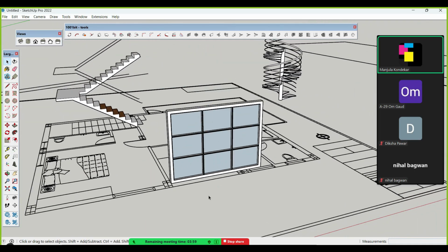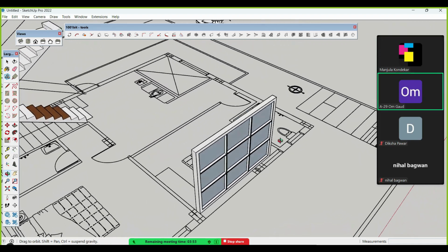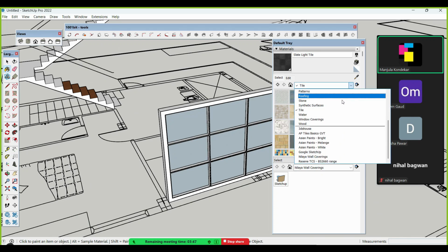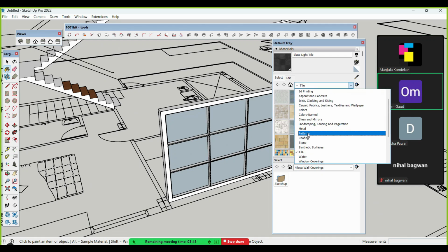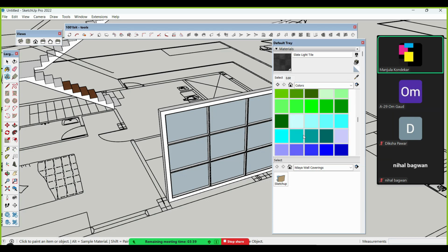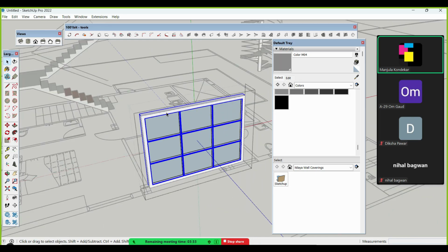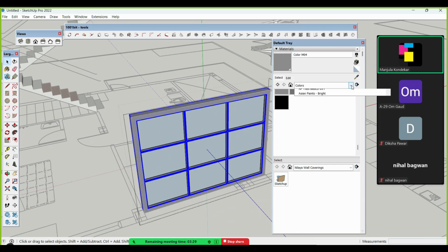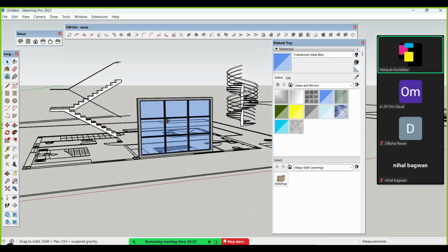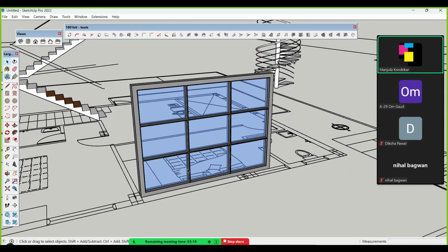See. Done. Yes, ma'am. Even you get a 3D also. And then you can go to bucket and you can go to the metal option or wood option. Let me go with the color. Later on I can change the metal in V-Ray Lumion. Okay. Aluminium. Go inside and apply. And I go to glass and I apply the glass material to it. Done. You can use it as a window or as a curtain sliding door.